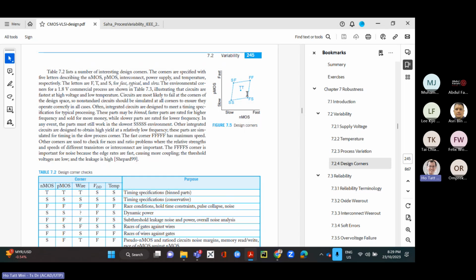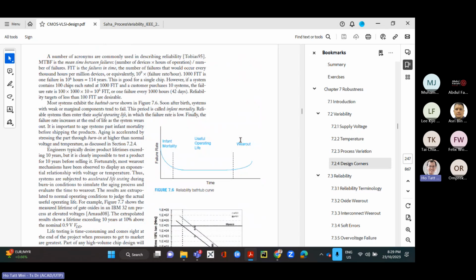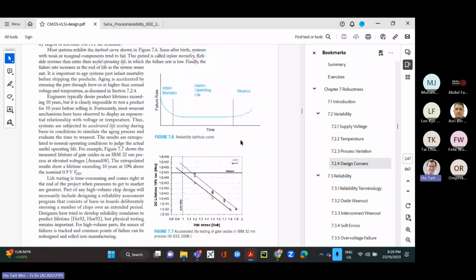And your Liberty file, the process development kit, also has the transistor models, the logic gate models, the standard cell models at these process corners. They have the fast and slow, FF and SS corners, right? So if you check what we've covered in the past sessions, or also in the Google Silicon Initiative, the 130 nanometer process or the 180 nanometer GlobalFoundries process, you also have the process corner models, the FF, SS, and TT corners, right?